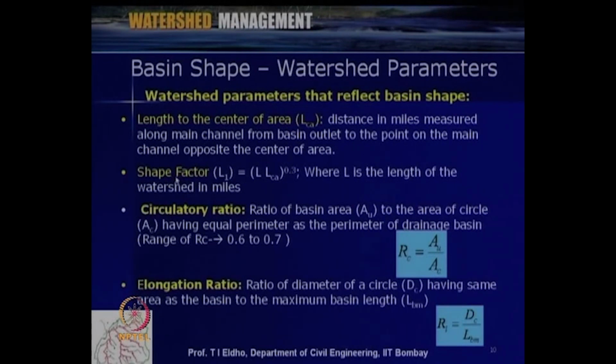Then another important parameter is the shape factor. We can define the shape factor as L into LCA to the power 0.3, where L is the length of the watershed in miles, and LCA is the length to the center of area.